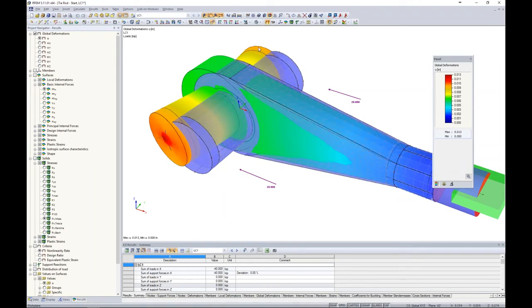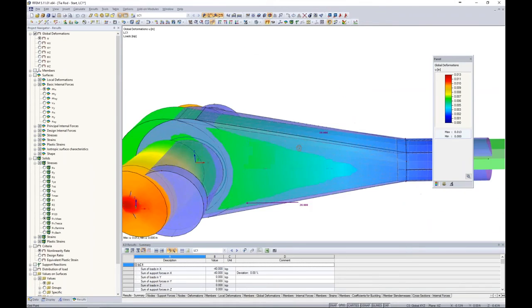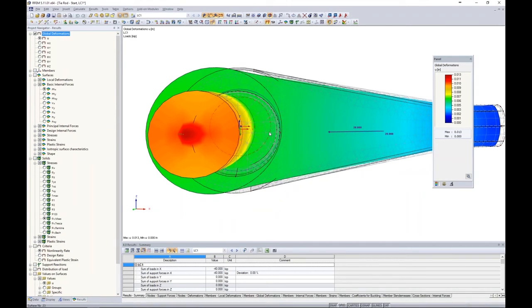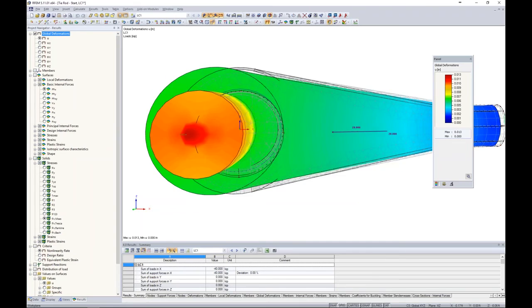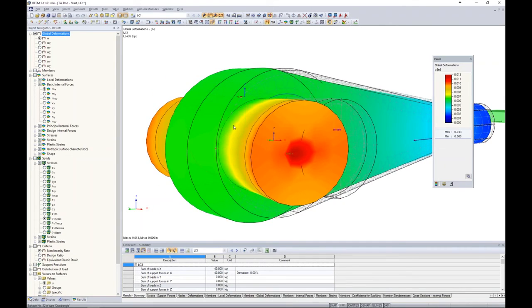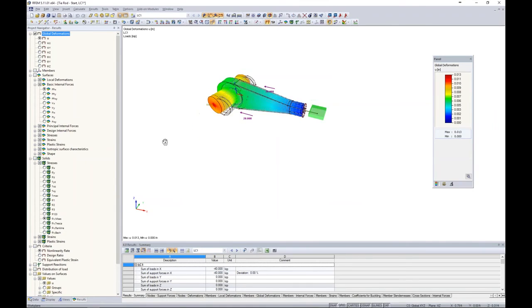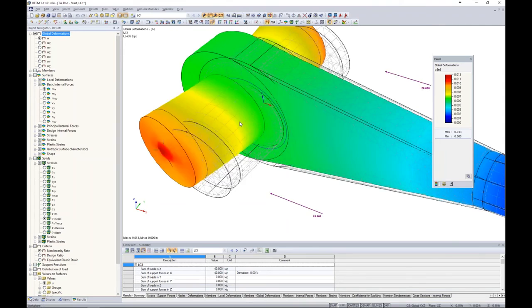So with this bolt element passing through the eye, and we turn this into elevation view and maybe into wireframe, we can see here that it looks like the bolt is fully fused to the front portion of this ring element. This is not really what's going to happen. In reality, what we would hope to happen is that this bolt would release away from the ring element where we have tension forces, but in the back, we would still have full fixity where we have compression, where the bolt's bearing onto the ring. So how do we exactly take that into account?